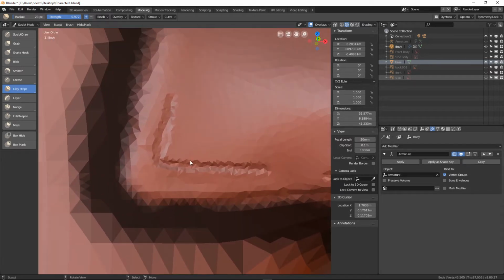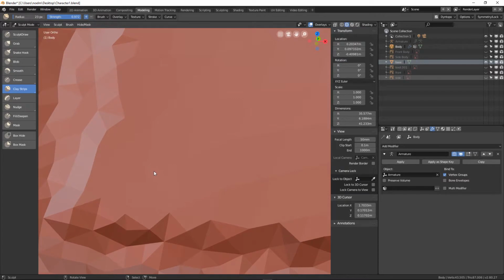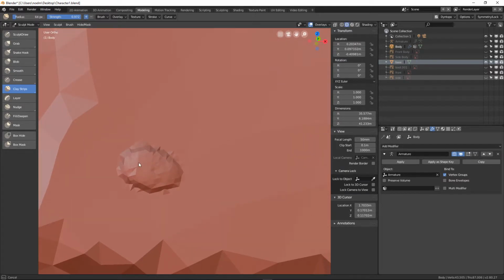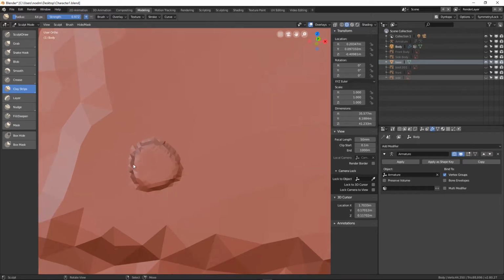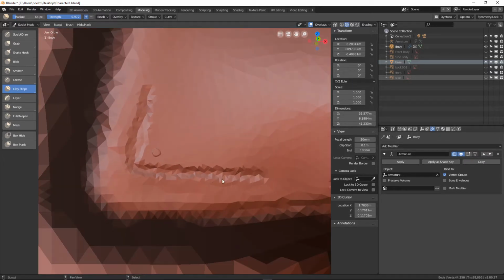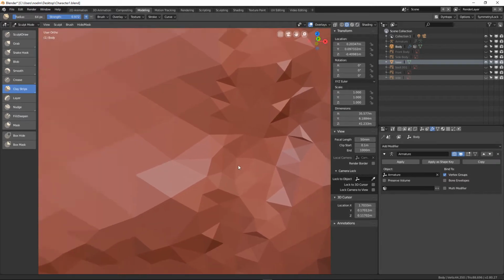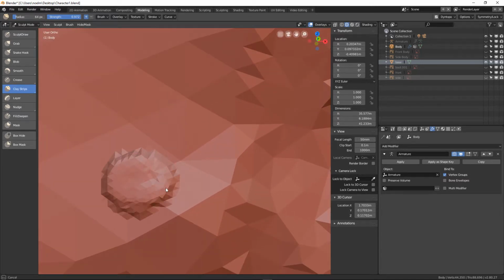The scale at which we draw is determined by how far zoomed in we are. So if I zoom in here and I want to add something that looks like maybe the top of a bolt or a screw, I can do that quite convincingly. Now the sculpt tools are not like polygon editing, so you're not going to get completely straight lines. That's not what this process is for. If you want a perfect circle, then you would make a circle. So this is for more organic shapes.